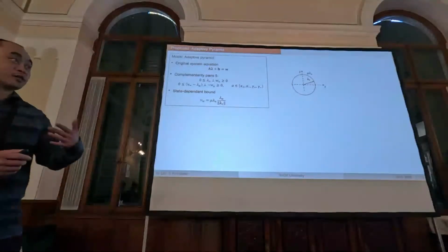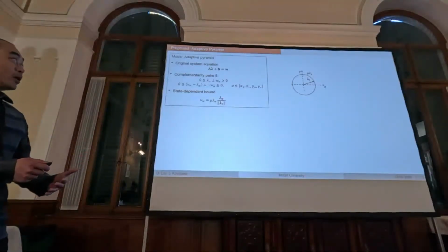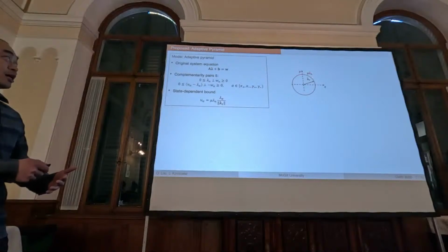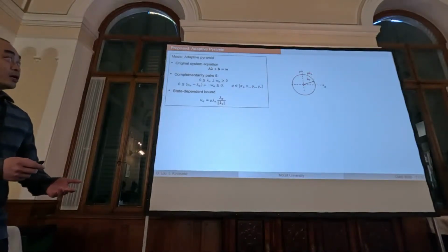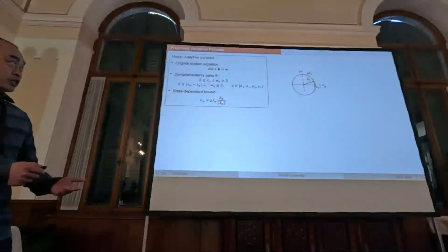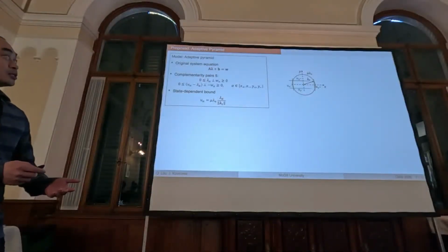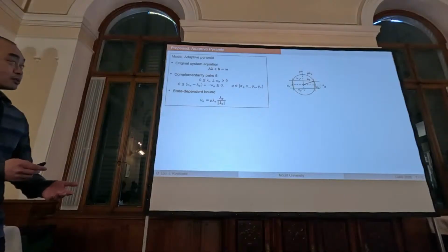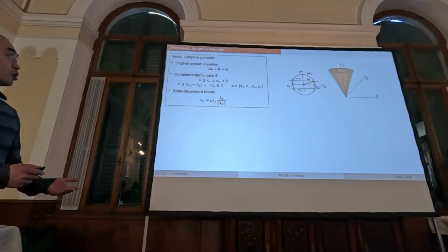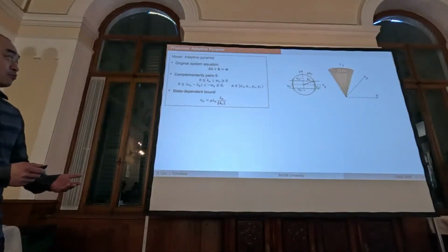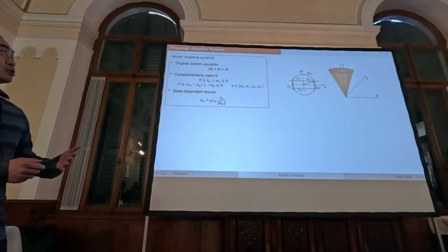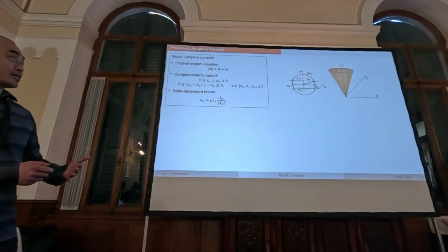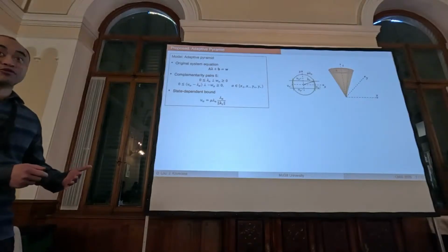Suppose we have already solved the contact state. We have the normal force from the circle and the tangential vector is here. Based on this information, the friction bound along the x plus direction can be drawn this way, as well as the other 3 directions. Therefore, the whole model forms an adaptive pyramid on the admissible side that, based on the current contact state, always aligns with the ideal friction cone.